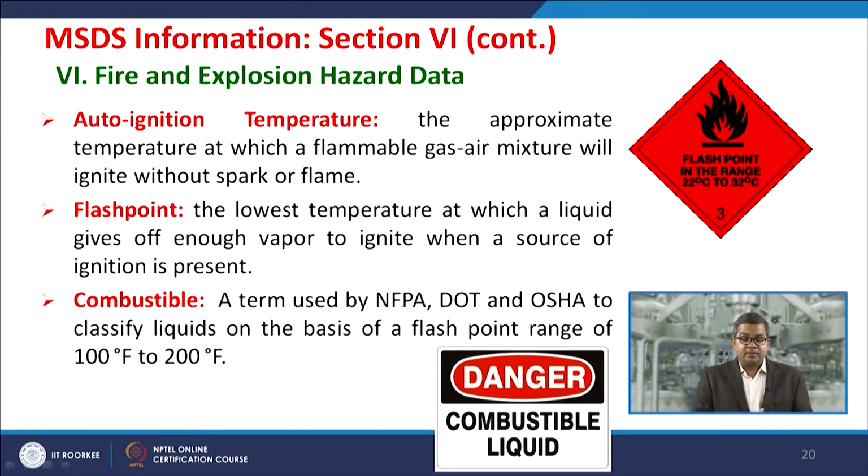Now, under this section, the auto ignition temperature must be listed, the approximate temperature at which a flammable gas air mixture will ignite without a spark or flame. The flash point must be listed, the lowest temperature at which a liquid gives off enough vapor to ignite when a source of ignition is present. The combustible is the term used by NFPA, Department of Transportation and OSHA to classify liquid on the basis of a flash point range of 100 Fahrenheit to 200 degree Fahrenheit.